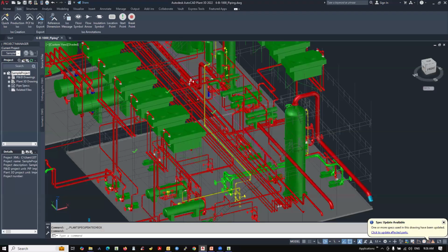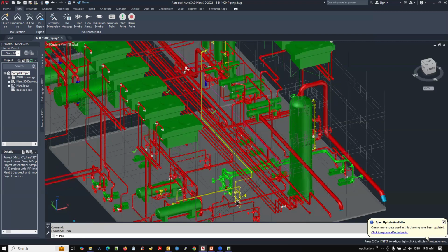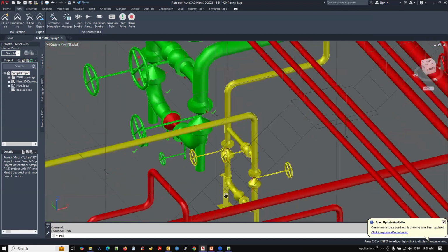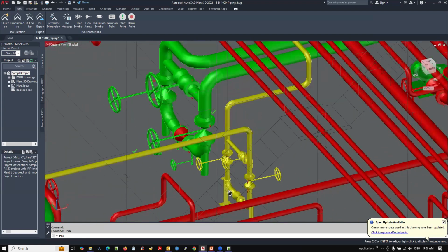Now here is the layout again. And for this presentation, we are going to be taking a line which is going from this equipment nozzle. You can see that. It goes and connects this yellow line, goes and connects the equipment nozzle here. So now let's say the designer has already laid out even the supports here. For example, he has put a support where it is not only stopping the growth in this direction, also in this direction. So there are 2 lateral directions.